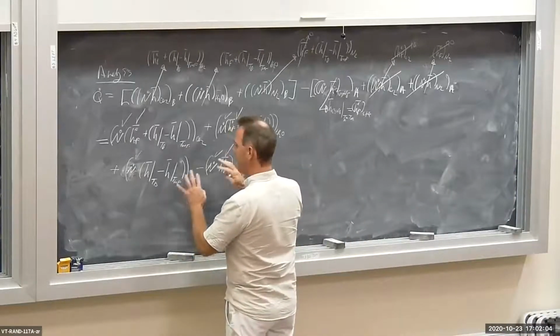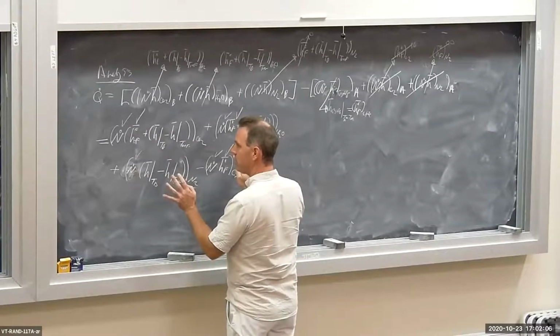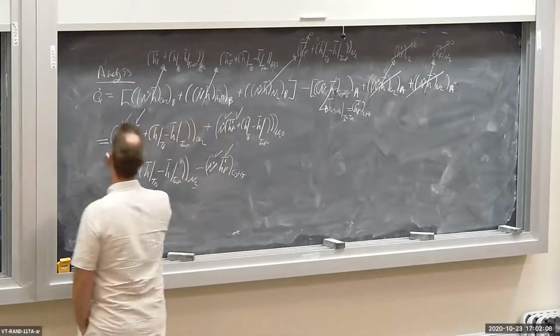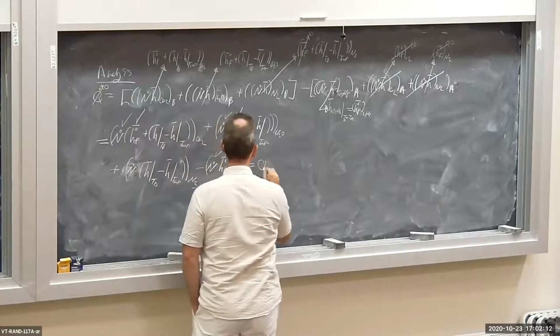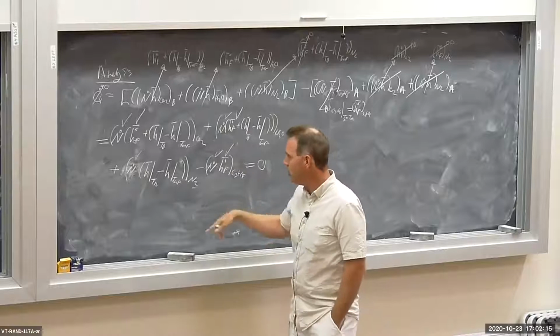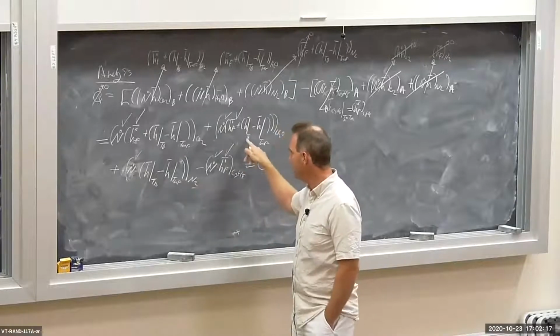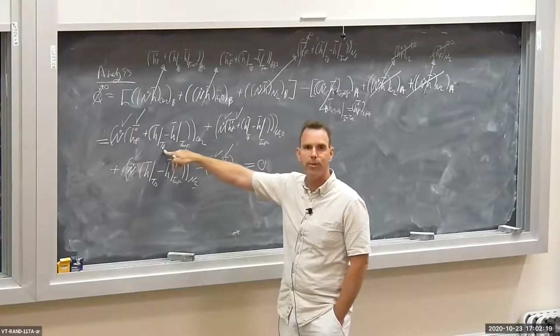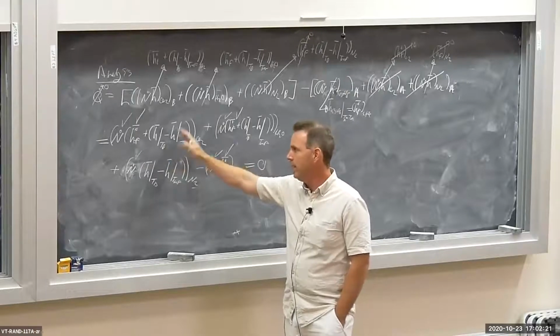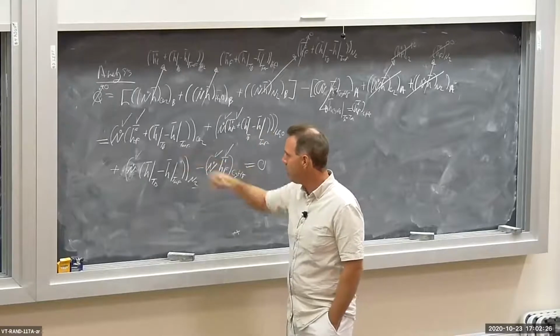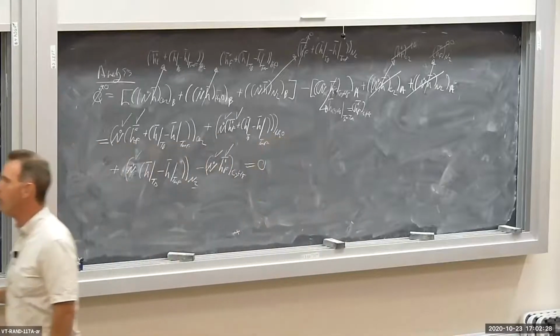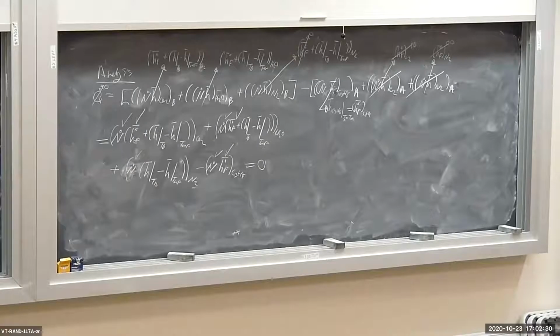If I can get everything in this equation fixed, and I know the heat transfer is 0, it's adiabatic, then I'll have a single equation which is only a function of quantities which themselves are a function of the outlet temperature. It'll be a nonlinear equation, but nevertheless, let me get the H bar at T refs. Let me get all those.